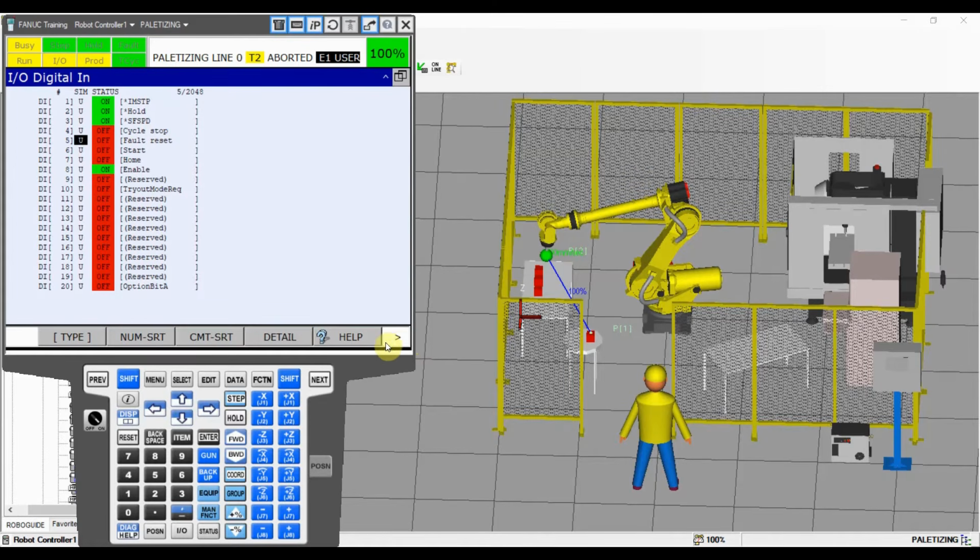So when you are in the digital input screen, you can see we have a simulate button in here and unsimulate. For the inputs, it's the same. If we get to the simulation column, we can simulate it. So we can simulate a state of the input and output. Why do you want to simulate the state of a digital output? Because maybe there is some data that you don't want to send to PLC. So you can simulate it, and whenever it's simulated, it will never change the state as long as you don't say so. Okay, going back to inputs.